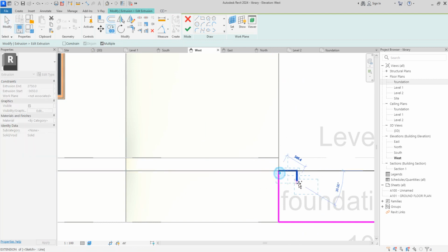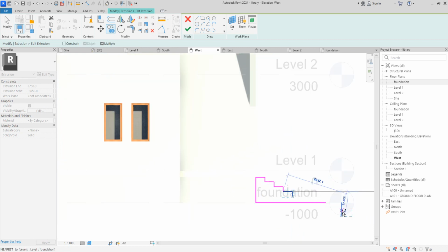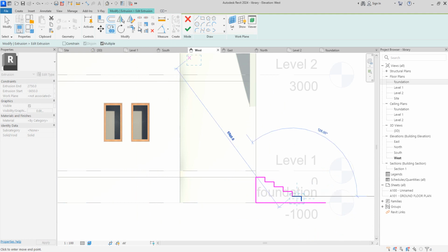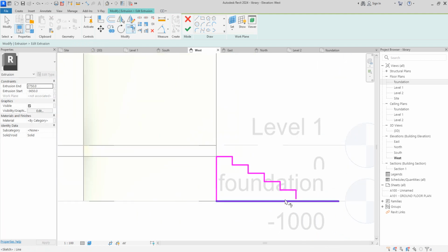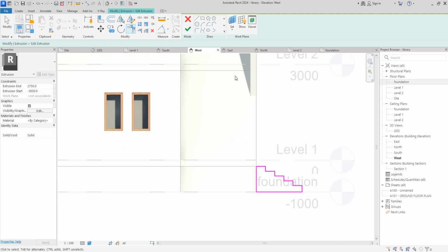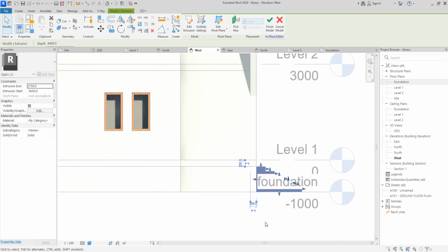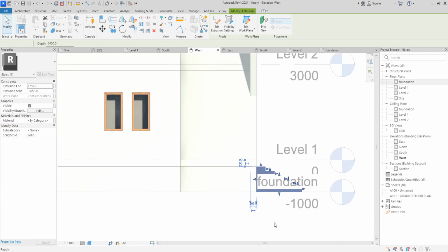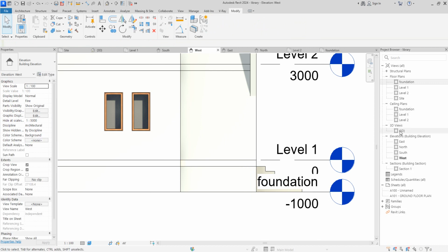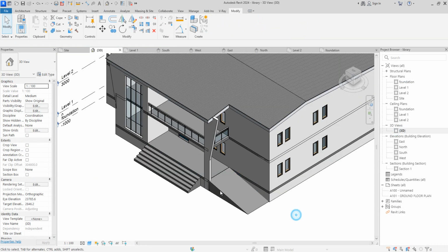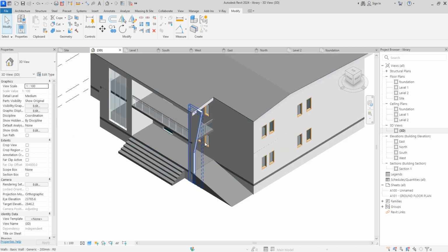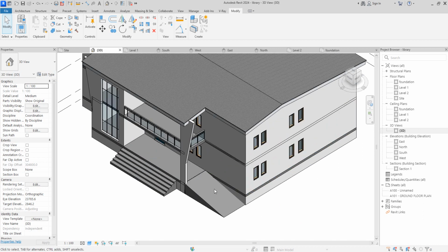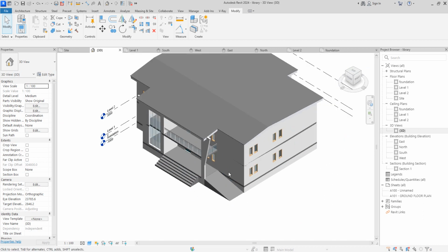Copy a multiple from here, drop it here, drop it here, drop it, then drop it at the last position. So the first step is always much higher. So it's a normal calculation for step design. So you're done with this, go to 3D and see your work. So elevations are coming, the ramp and the steps, so you can enter into the library comfortably. So that one is done.